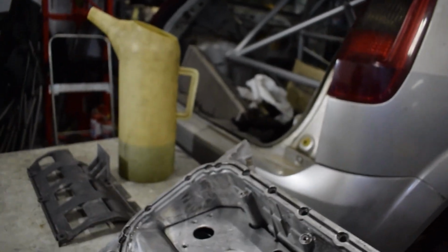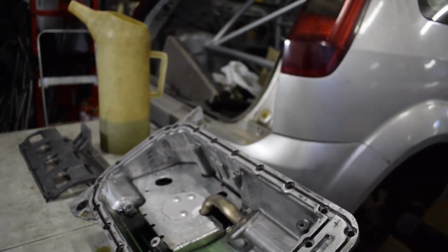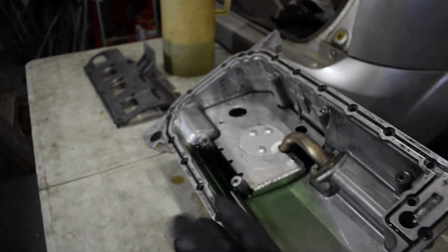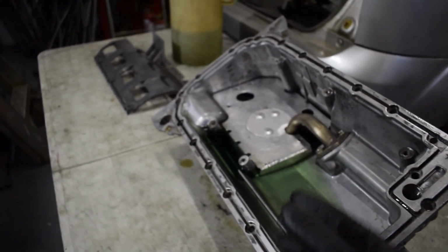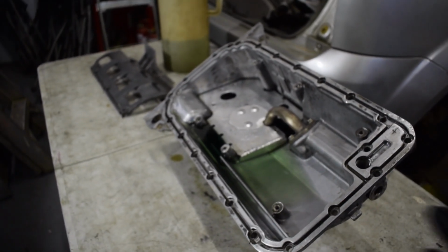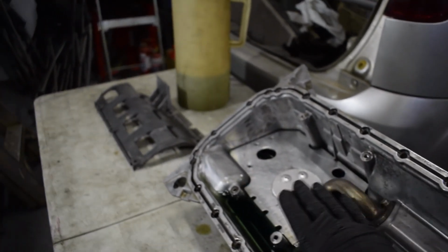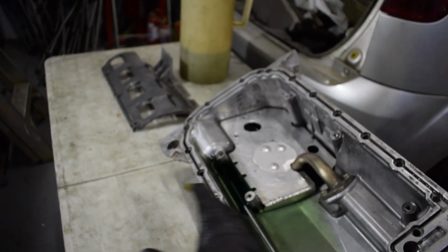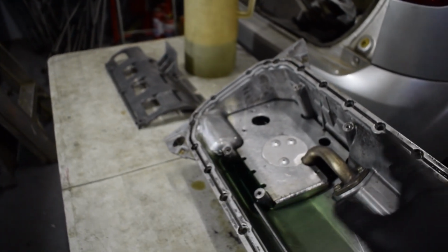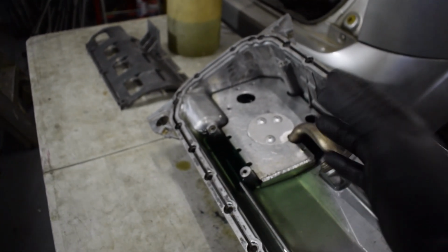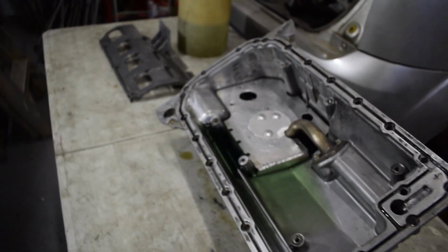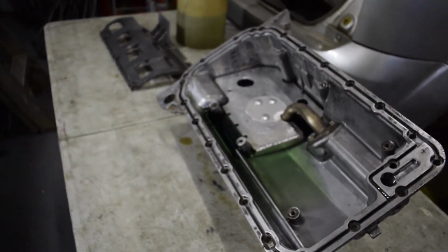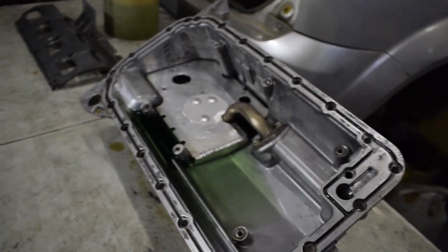So that means there's quite a bit of oil above the line, and the problem with that is as the oil sloshes, it carries energy, and that comes down to particle flow, etc. If it's sitting above the line, it carries the energy to pull it as it flows up under surge and the cornering loads. It then draws additional oil with it, and if there's a pathway for it to go, obviously it's just going to follow that natural path.